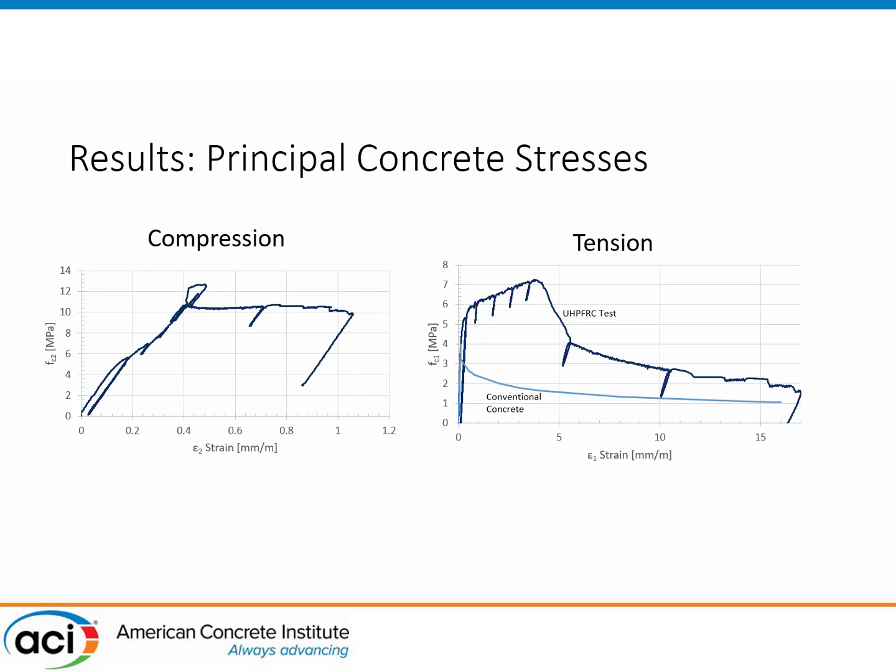The curve in the top, which of course, if you know your energy principles, is physically impossible, what that actually indicates is that we had a crack that was partial width to the specimen and not the other half of the specimen, which meant that the instrumentation on the surface, which in our calculations assumes a uniform strain field, did not see a uniform strain field. But once we kept on pulling, that went away. We ended up with basically a plastic behavior going out until we ultimately unloaded. No sign of crushing of the concrete. We probably can't crush this concrete with our machine.